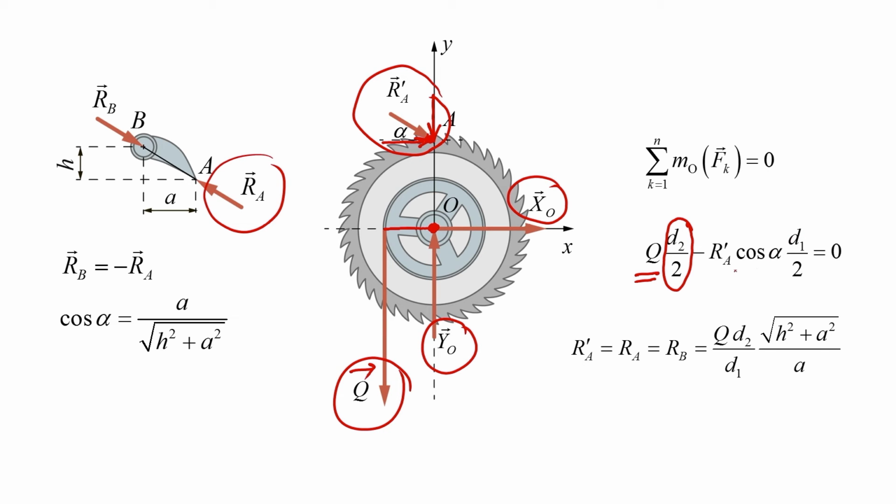For the component RAX, the moment is equal to the magnitude of the force times the arm, where the arm is the distance between the point to the line of the component's action. The component RAX is tending to rotate the body clockwise, so it is included in the equation with a minus sign. Let's define the unknowns from the derived equation.